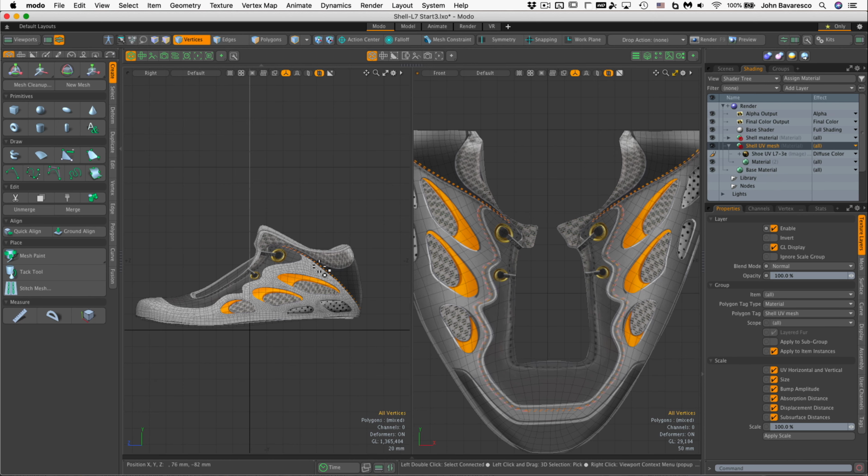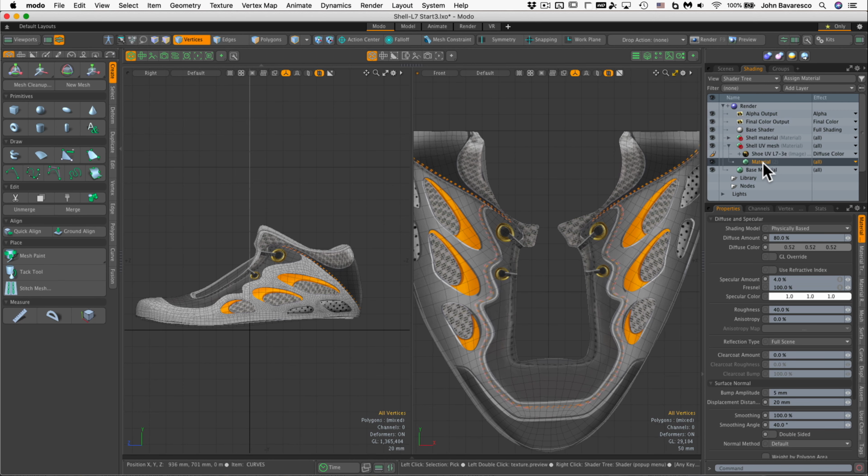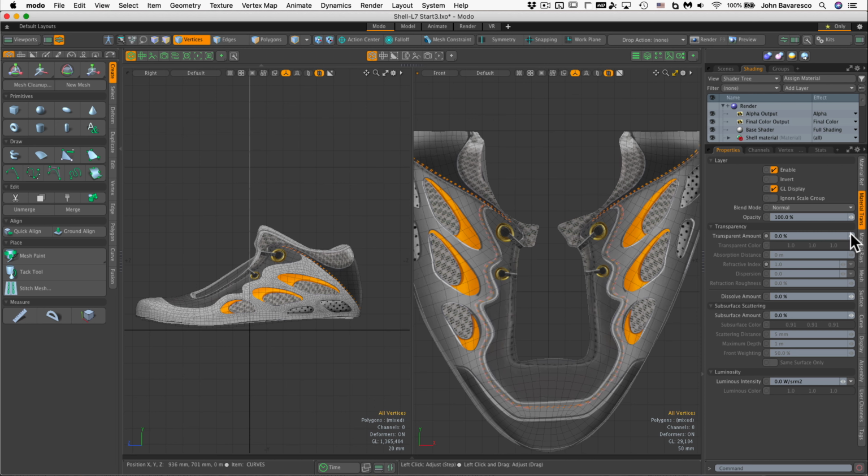I'm just going to select the material, and I'm going to go to the material trans here. You can see that edge tab there, and I'm going to go down to where it says transparent amount. I'm just going to click and drag this transparent setting up, and you can also set it here. Just plug in a number. As you can see, the background image becomes more transparent. Actually, my whole background object becomes more transparent, and now I can see my curves. They show up really well against that background image, and I can still see the background image well enough to lay my curves down on them.